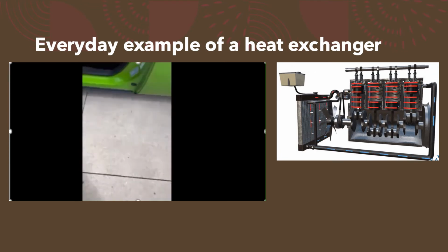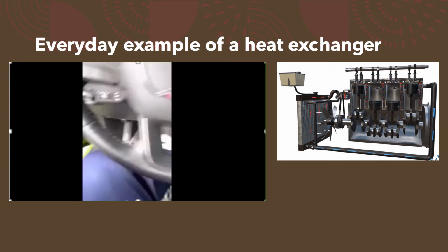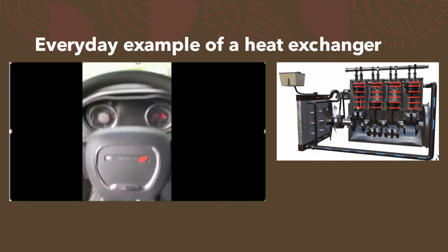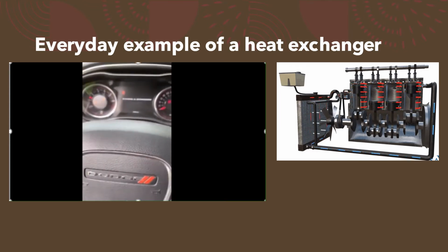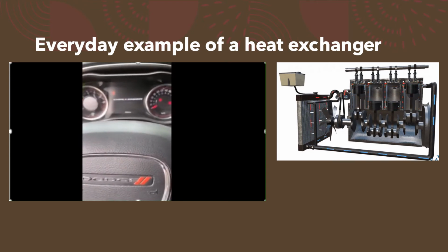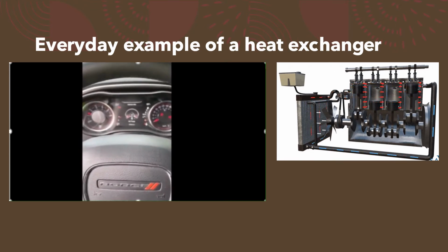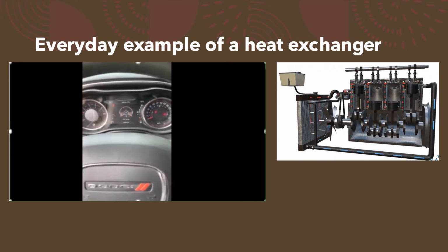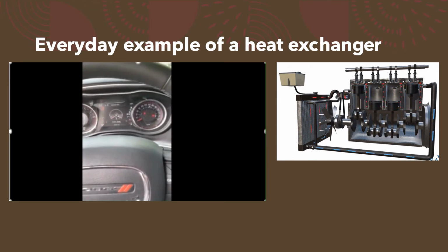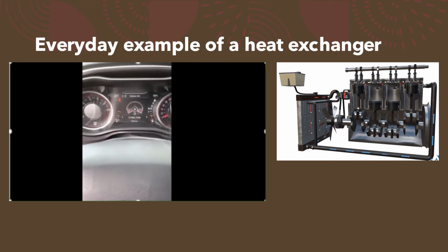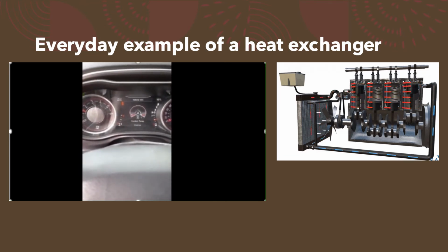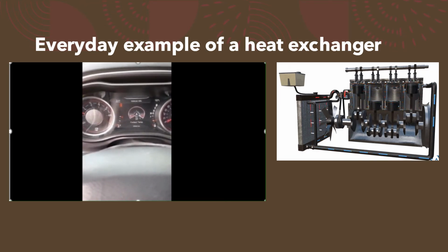Once the coolant reaches a certain temperature, the thermostat will open the mechanism to allow the coolant into the radiator. The hot coolant will enter the top and flow horizontally through the radiator. The cold air will flow perpendicular to the hot coolant. The coolant will flow to the bottom and exit at a cooler temperature. The coolant will then be reintroduced into the system to repeat.